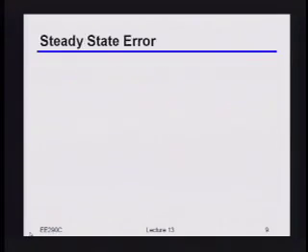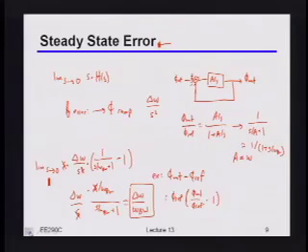Okay, so just to come back to here, we said that if we really did have this plesiochronous system, with that CDR that I drew before, then we again had this bad situation where we have this trade-off between how fast we can track those ramps, and therefore how much static phase error we get, versus how much we can filter out the ISI jitter. Okay? So what do you guys think we're going to do? How are we going to fix this problem? We have the same problem in a PLL. Yeah, there we go. Exactly.